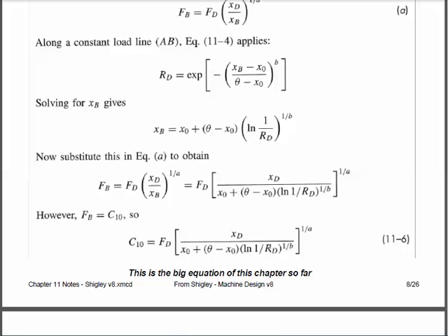But once I've chosen the force I intend to put through the bearing, the life that I need it to last, and the percentage of failures that I can accept during that life. And the standard catalog life is 90%. But what if I'm trying to get to Mars on a machine and I just need superb reliability? I may need every bearing to have a 99% reliability, or maybe even a 99.9% reliability, because 90% would not be acceptable. If I know the load I want, and I know the life, and I know my reliability, plug them in and solve for the catalog number, and I go to the catalog and I grab a bearing that can meet or just barely exceed this number, and I will have a bearing that will get the job done.